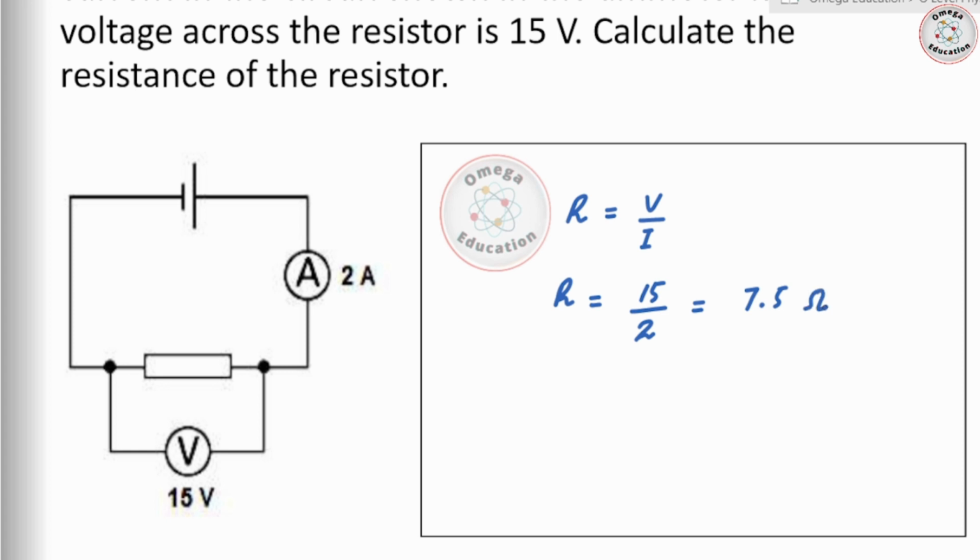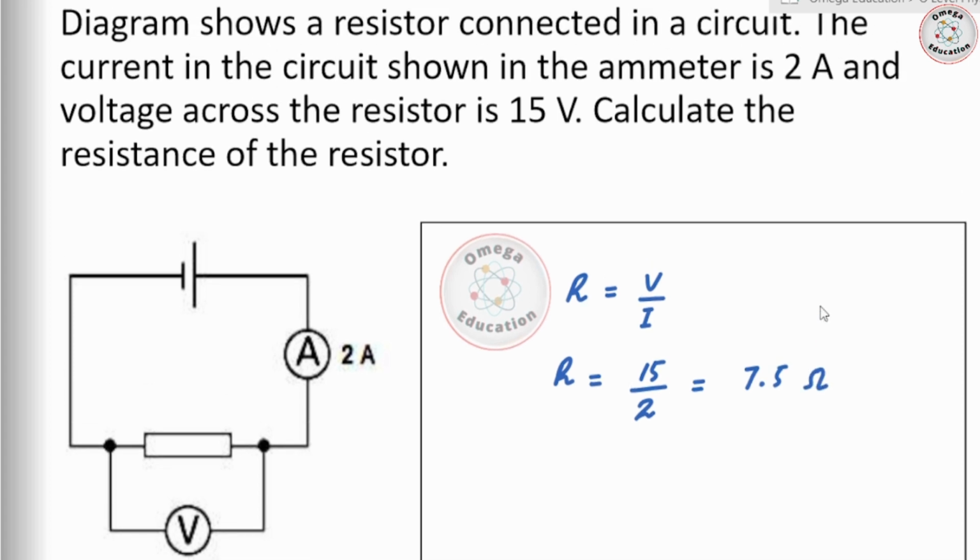And if you connect the ammeter in this case, positive with the positive terminal of the battery, the ammeter has two terminals, a red terminal and a black one. So the convention is you connect the red terminal, which is the positive of the ammeter, with the positive terminal of the battery, and the reading it would give, if it is a digital ammeter, would be positive.